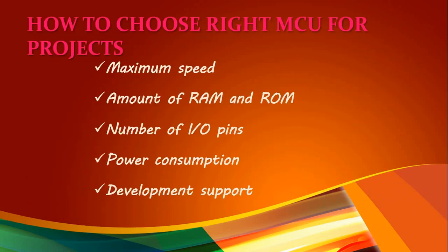So how to choose the right microcontroller for a project: while selecting your microcontroller, you need to consider what type of microcontroller you need to use, how fast it is, how much RAM and ROM space it has, the number of IO pins, its power consumption, and what software it will support. All these things you have to know while designing a microcontroller project.